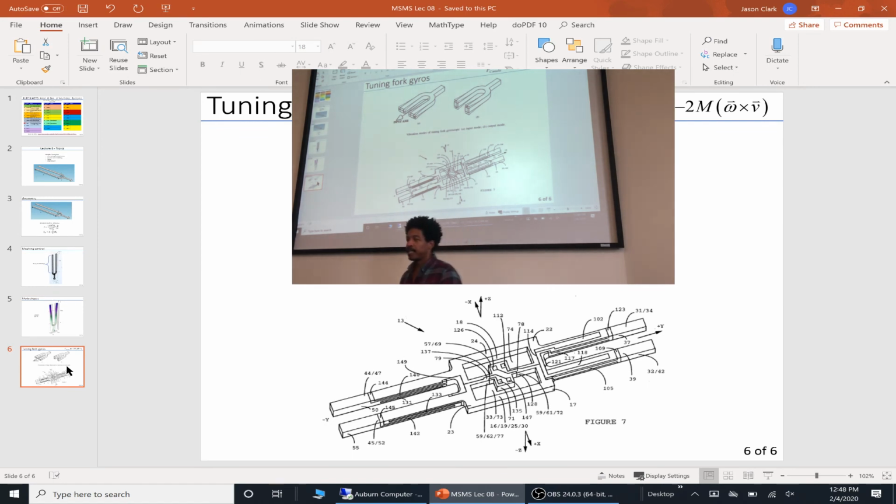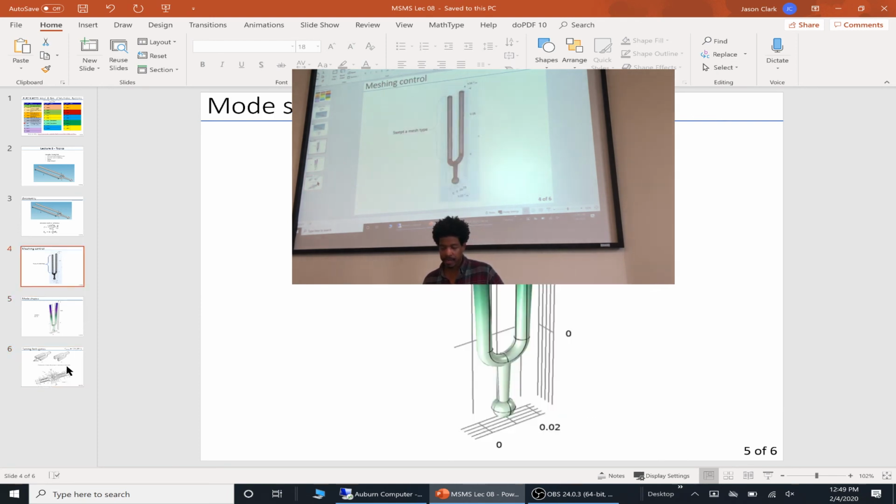You have them in your car. They help manage your stability control. They have them in little unmanned air vehicles, right? Here's one such device right here. This is actually a MEMS tuning fork type of gyro. It's made out of single crystal material, and it has electrodes that measure how it's vibrating and actuate it to get it moving in that direction, and then it's able to sense in the vertical direction.